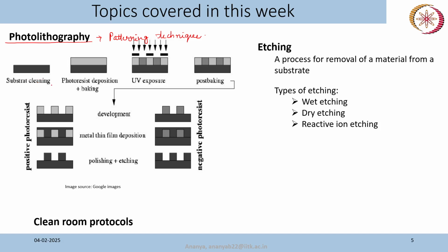There are different cleaning methods. It can be a basic solvent cleaning, where you clean with acetone, IPA and DI water. It can be a piranha cleaning. If you want to make a good device, then you always start with a clean substrate. Now after cleaning, you apply photoresist on the clean substrate. How do you do this? Generally this is done using a spin coater.